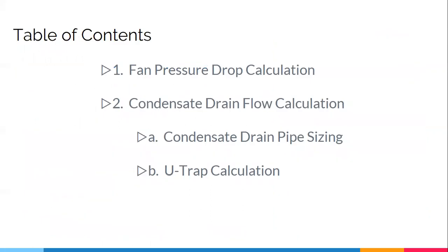So for tonight, we are going to learn two things: pressure drop calculation and condensate drain flow calculation. As part of the condensate drain flow calculation, you will also see condensate drain pipe sizing and the U-trap calculation.